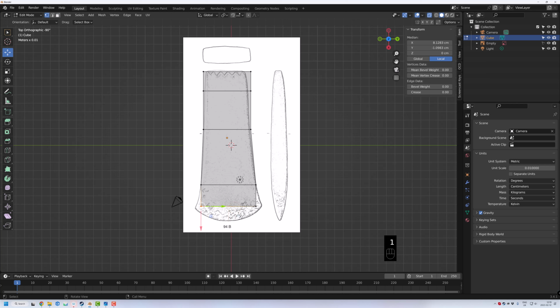and then go back to 1, and we will select these ones here. Move them to the edges, roughly. Let's do these two up here as well. There we go. So the reason I'm not extruding this one out at the bottom is because I want to do a loop slice. So I'll cut it this way instead and then just move them out. This will give me cleaner geometry in the end. So pressing Ctrl R, I'll then do a loop slice, one roughly around here, and another one probably somewhere around there. And I can just drag these down.